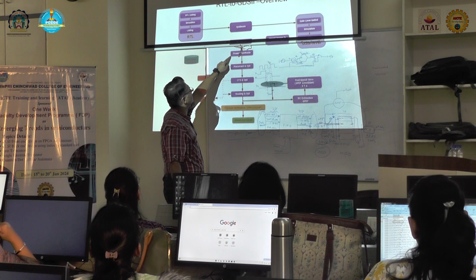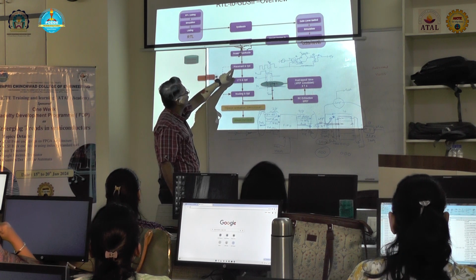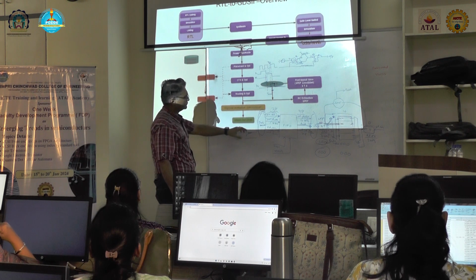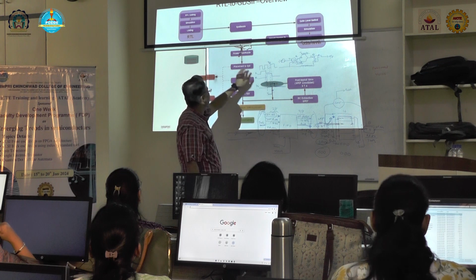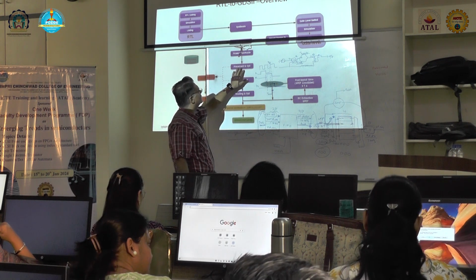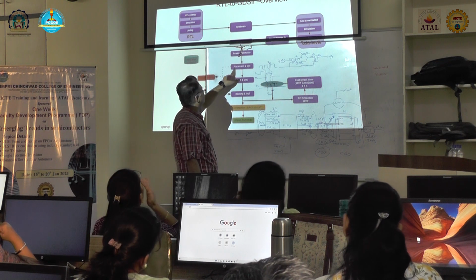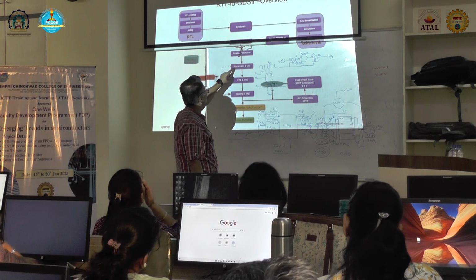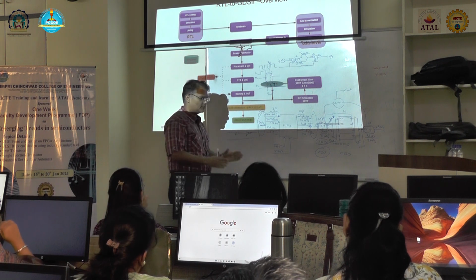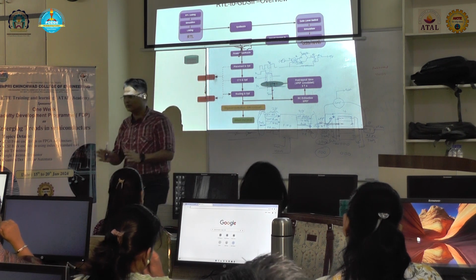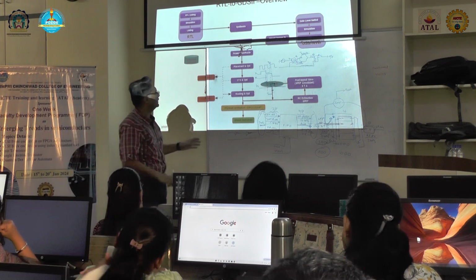After the power plan routing is done, the next step is placement and optimization. In placement, it will try to fit whatever logic you have given. So you have completed the power plan, then you are doing the placement here, and in placement you are just placing the small blocks. You are not doing anything else.